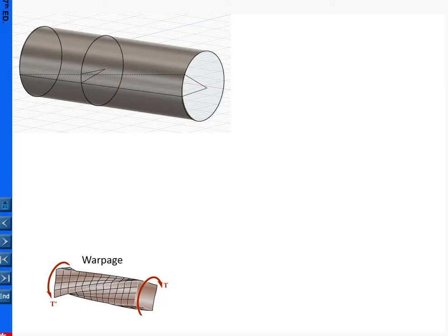So here I try to come up with a schematic diagram to better explain the assumptions we're going to make. Basically, when we study torsion of the shaft, we assume the shaft is uniform. That means its radius, let's say C, is a constant radius throughout the whole shaft. If we apply the torsion here, due to equilibrium, you should be able to find that on the other side the torsion is T. Okay. Let's take a look at the further details about the assumptions we're going to make.